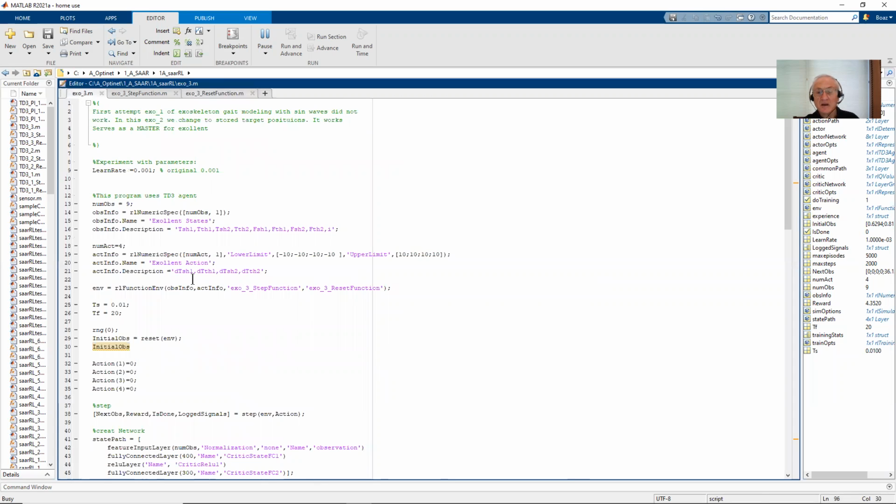The action in our example is the reinforcement learning forces which are applied, or torques which are applied to the system in order to change the posture of the torso, as well as the angles of the joints. So this is on top of a PID control, which is very robust and does most of the work.